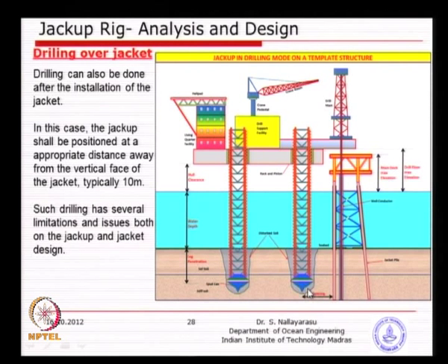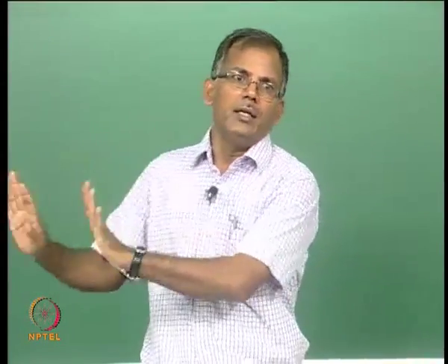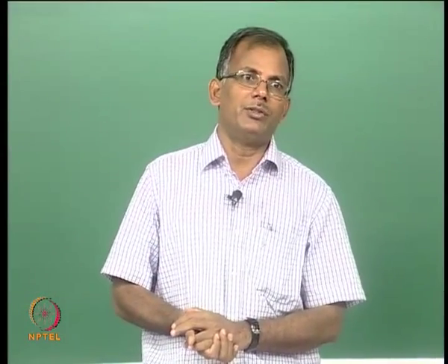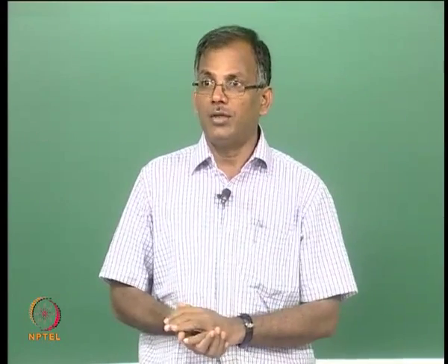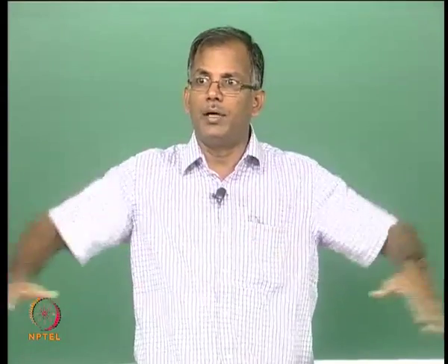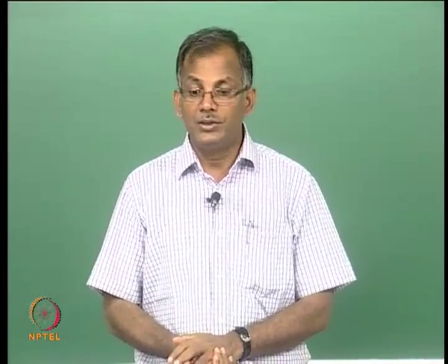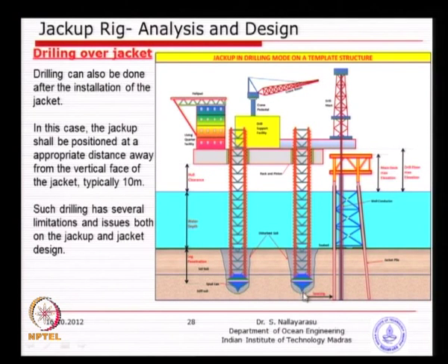When the leg is penetrating, the soil is getting squeezed away, isn't it? Soil is going to have a horizontal movement putting pressure on the jacket piles, which you may think is just very small. Actually, if you look at the size of the spudcan going down and the volume of soil replacement or soil pressure, you will see that the stresses on the pile could be substantially larger. So we need to make sure that conditions are evaluated and designed accordingly.